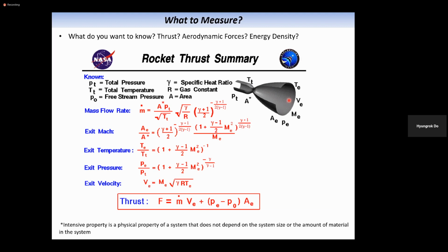With the axisymmetric assumption, maybe along a line that is passing through the center of the nozzle exit plane, you can measure the velocity field, and maybe that is sufficient for estimating the velocity field on the exit plane of the nozzle. Okay, so now you need a one-dimensional velocity profile measurement. And the other one is the mass flow rate.